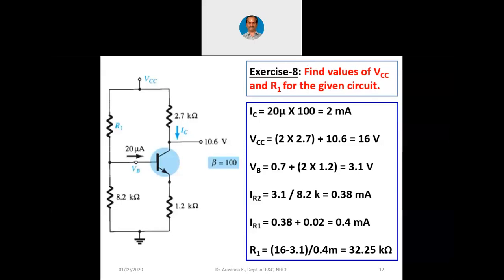So because of this particular switching activity, we also note one more point as far as the common emitter configuration is concerned. That is that output and input will have a 180-degree phase shift. Means if you give a sine wave with the positive cycle and negative cycle at the input, at the output you will get the negative cycle and the positive cycle, which means there is a 180-degree phase shift between output and input.